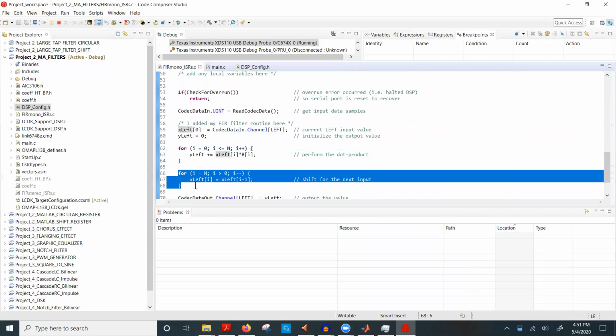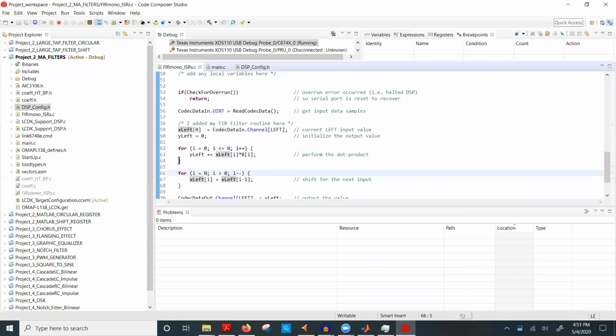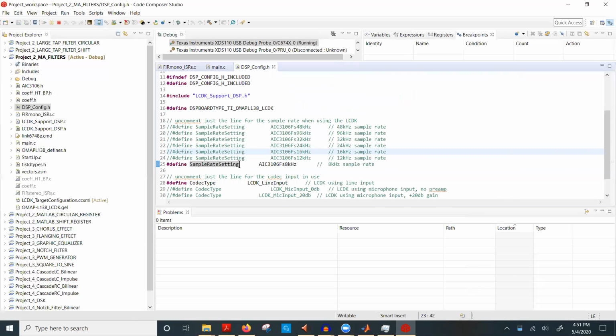And we want to be efficient with our code because our DSP processor can only perform a certain number of operations before the next sample. So with our DSP configured, I have it set to the lowest sampling frequency, 8 kilohertz. That means it takes 8,000 samples a second. So before the next sample comes in, the DSP board has to calculate the result for the current sample.